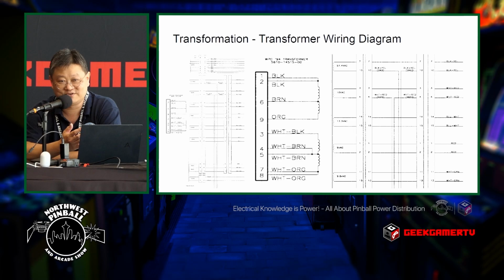Now, if I put the 0 reference point at 0 and I'm trying to run a sound system and the whole difference is 24 volts, well, now the difference between ground and the highest value is 24 volts. And if I do something incorrect with that, I could shoot 24 volts instead of 12 volts and fry something. And that's part of the reason why. It keeps the numbers a little bit lower. It makes it a little bit harder for people like me who aren't really good at analog to look at things and say, why would you do this? But that is my understanding of why it's done.